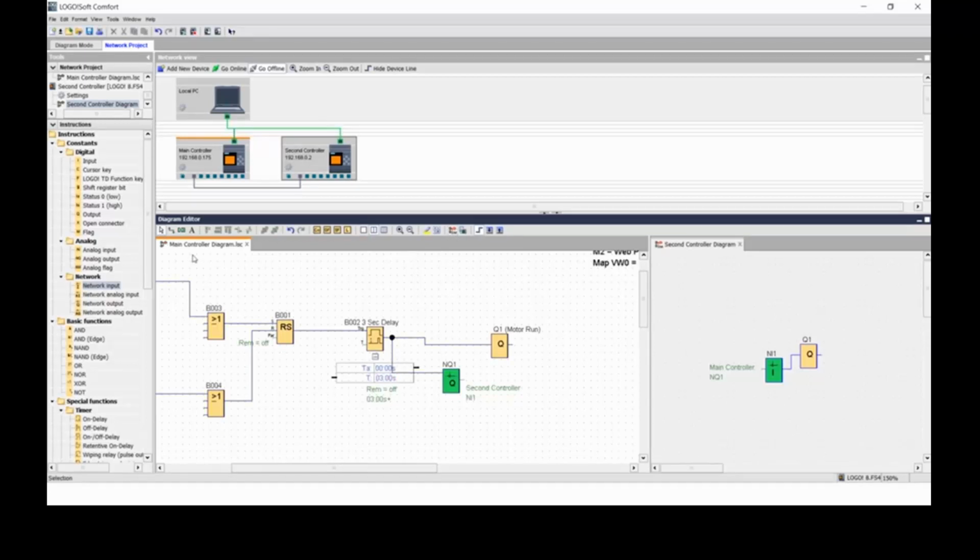Being simulated at the same time. And therefore now when I start my push button, the timer is ready to turn on the output here, but it also turns on the output in the opposite program as well. So we've tested everything in terms of configuration, and the logic in the user programs is all sound before we even hit site, and then we know that if there is a problem with communications, it's going to be in a configuration